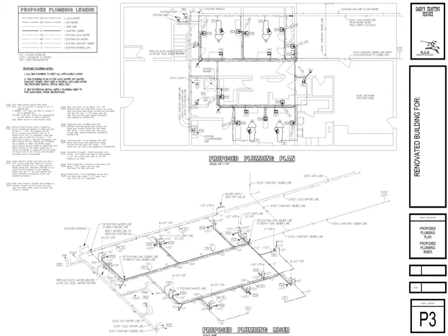For those of you taking the plumbing inspection class, you'll be examining these drawings some more, and we'll discuss them in more detail later in this course. But here is a riser diagram at the bottom of the page, and it details an entire plumbing system in this axonometric style drawing. In this case, we are getting some detailed information about how these all come together, but it's more diagrammatic than precisely where these pieces are installed.